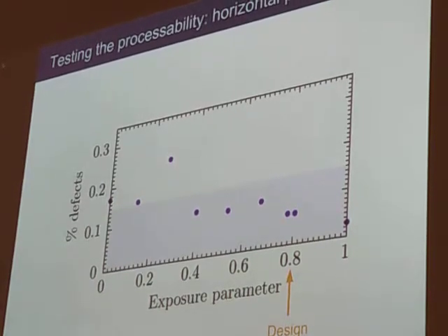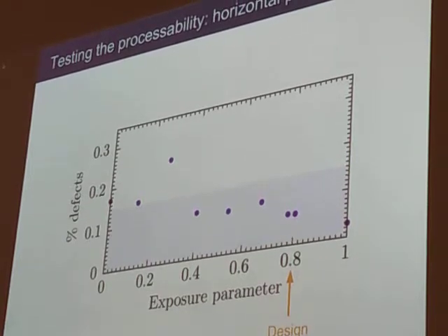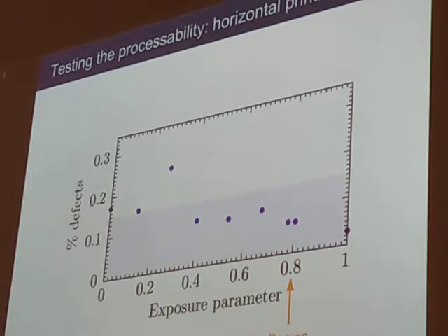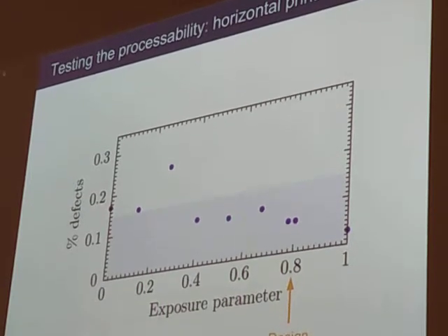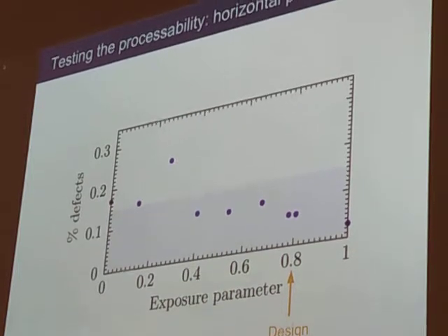And it's even doubly more complicated because as you're using the alloy in the engine, it's operating at about 900 Celsius, and so the size of the precipitates changes. You've got to get it right at the beginning of this life cycle and also correct at the end of the life cycle.